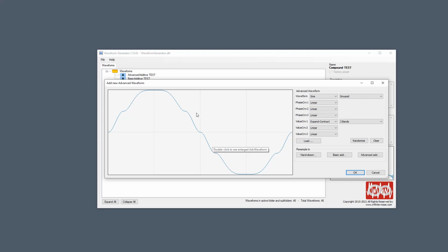And that part we are both expanding and contracting. That will introduce this ripple effect. So as we increase it, we'll have small ripples here. They're hard to see. You can see it's not a perfect smooth sine. But as you increase it, these ripples will be fewer and larger.